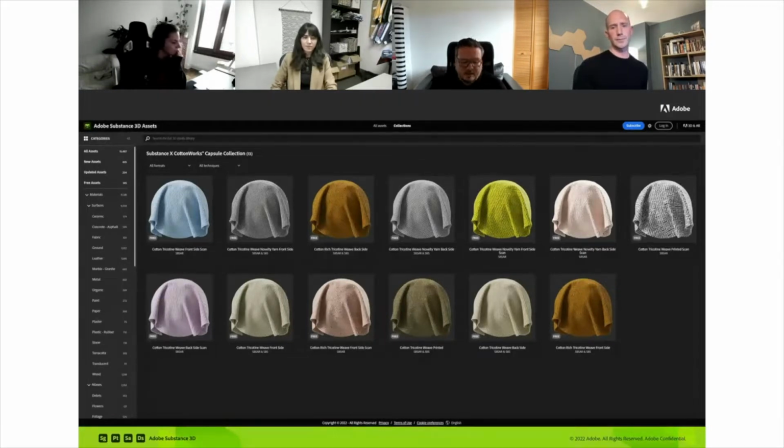Yes, of course. Procedural generation is entirely digital, meaning that it's a generation of the visual attributes of a surface using Substance Designer, which is a node-based graph generation tool, which enables, thanks to algorithms and filters, to create effects that then become a texture, or the several components of a texture, like the color, the roughness, the specular, the height, and the normal, and these algorithms combine to create these aspects.